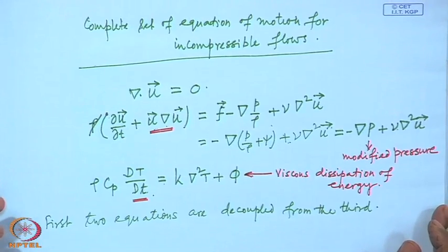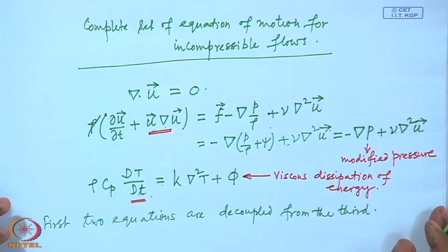However, it is also so that in most cases, or almost in all cases, even the tangential component of the relative velocity is 0 on the solid body. Of course, when you are talking about velocity, you are talking about relative velocity. So, both the tangential and normal components of the relative velocity are 0 on a solid surface or on a rigid boundary.